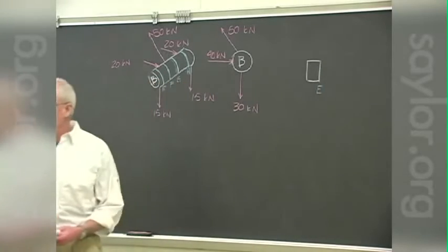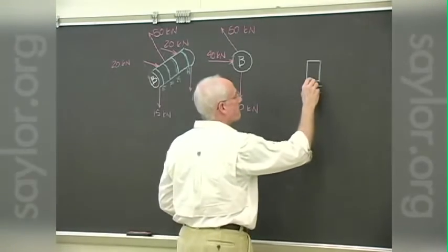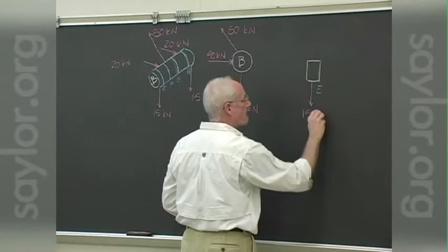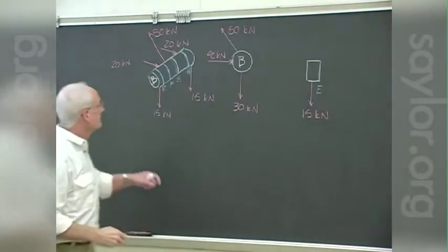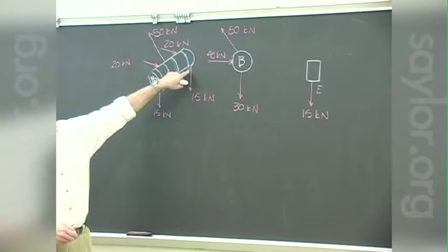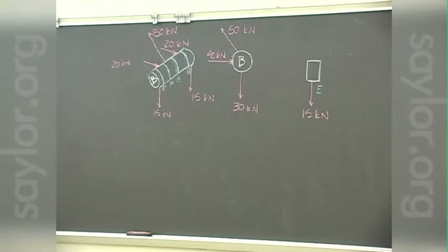What shear load is on that face? And is that the face of concern? That's maintaining just one of the 15 kilonewton loads. The same thing is going on at face H, just flipped around, the mirror image of it, so we don't need to look at that.